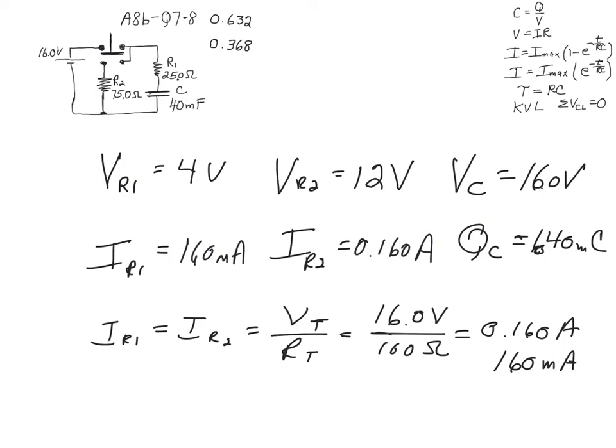Quite simple. The 0.16 times 25 gives us 4 volts, and 3 times the resistance times the same current gives us 12 volts, and there's our 16 volts. Of course, one of them has to be negative, so the sum is 0. So now, in this situation, nothing is charging. Everything is discharging. And so you can calculate the next set of questions. Let me put that out.